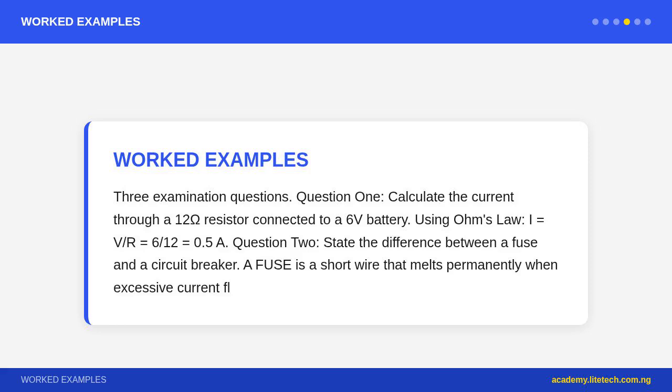Ensure all connections are secure, no loose wires. Use correctly rated fuses; do not replace a 3A fuse with a 13A fuse just because it will not blow. Do not overload circuits; use a surge-protected extension board if needed. Earth/ground connections must be intact for appliances with metal cases: washing machine, electric cooker, generator.